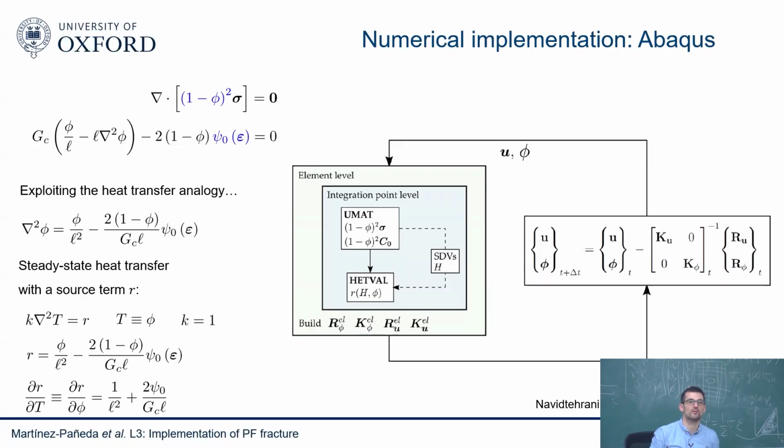That's the idea. So you multiply that with the variable you want. Like, I want to see the temperature variation spatially in my specimen. If I get my phase field and multiply it with the actual temperature, will I get the variation? Abaqus will solve for temperature, thinking that it's solving a thermomechanical problem, but it will actually be solving this equation. So what you will get as a temperature distribution will be your phase field distribution, and there will be no temperature whatsoever. You say, Abaqus, plot me temperature, and you will see something between 0 and 1 with all the cracks going around, and there will be no temperature. If you want to get temperature, you can't, because you are not really solving any realistic heat transfer equation. You're just solving a phase field equation.